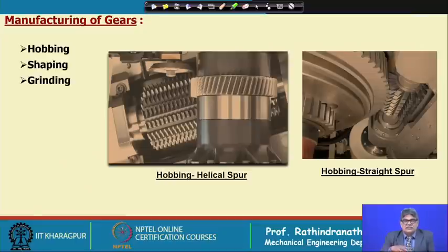These motions are linked inside the machine by a mechanism, and in that way teeth are ground, but the profile is maintained. Now, apart from that, it is also possible to form the teeth by hot rolling of the teeth. In some cases it may also be cold rolled.